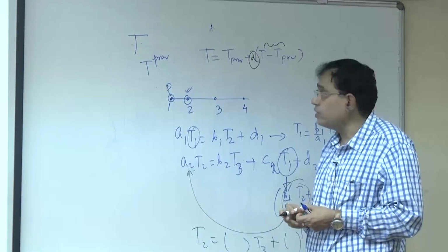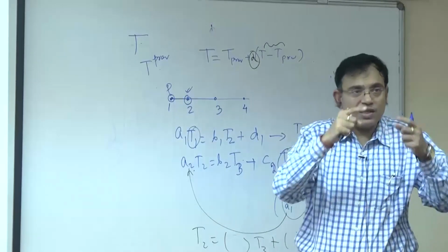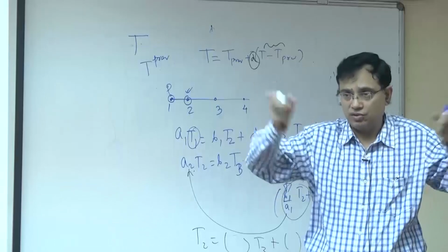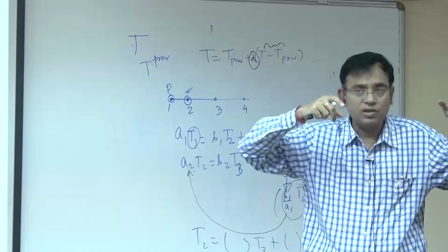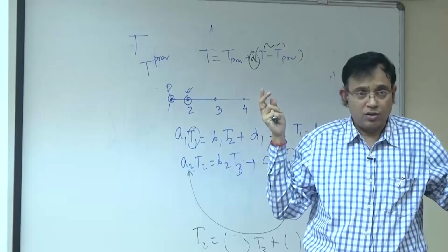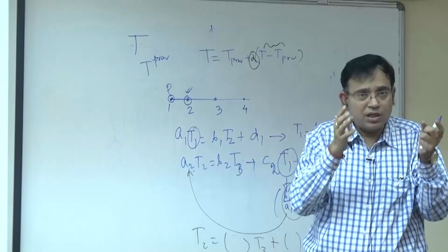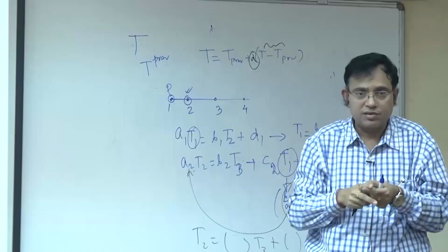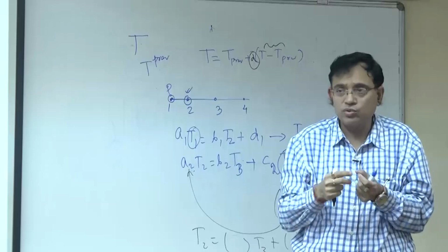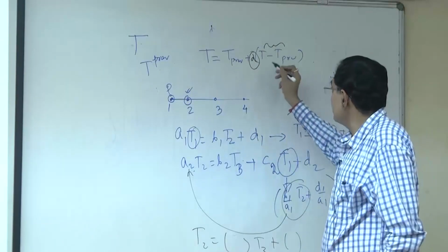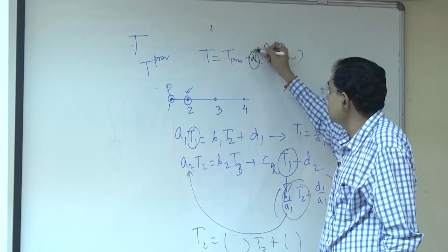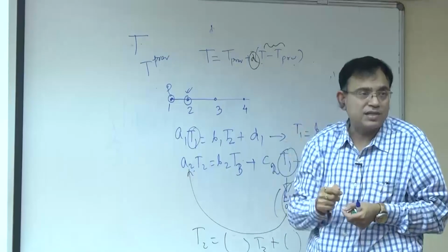So, what I will do is, see, you are starting with a guess and iteration is moving. Sometimes iteration is out of your control, it is taking the solution, diverging, that many times students say that, sir, we are running it but it is diverging. So, my only recommendation, if everything else goes fine, you control the change, perhaps with every iteration it is changing too fast. So, what you do? So, this is your change. So, to control this change you use something which is between 0 to 1, but typically less than 1.